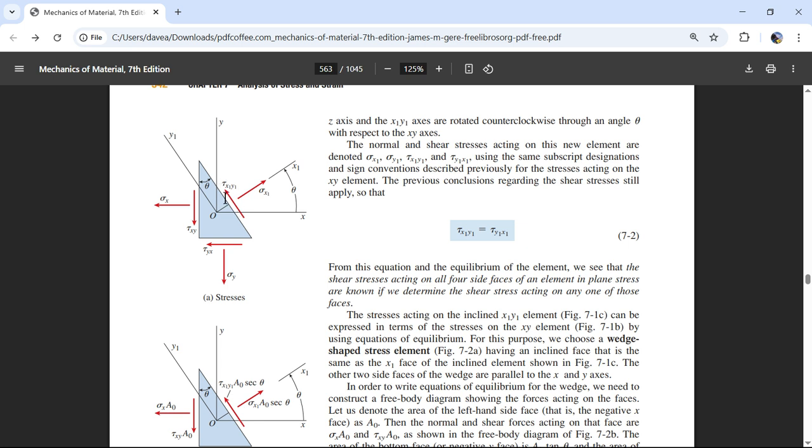Now this is a shear pressure, a shear stress. Stress has units of pressure: pascals, newtons per meter squared, or psi, pounds per square inch. So I can know the force on this face. It would be the same as taking some duct tape, taping it to this face, which has some thickness into the page, and then pulling on that duct tape. That force is applied over that surface, and so I can know that shear stress.